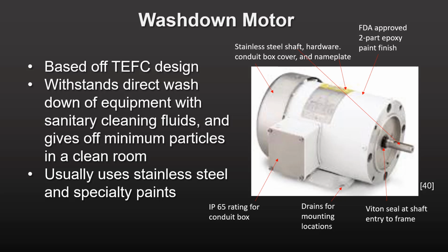This type of motor also gives off a minimum number of particles in a clean room, which makes it useful for semiconductor applications. The major design enhancements above a TEFC motor are the stainless steel shaft hardware, conduit box cover, nameplate, and FDA-approved epoxy paint finish. There are even drains on the motor feet for the washing fluid to drain through, just like those in a shower. The Viton seal at the shaft entry to the motor seals the inside of the motor from fluid entry.